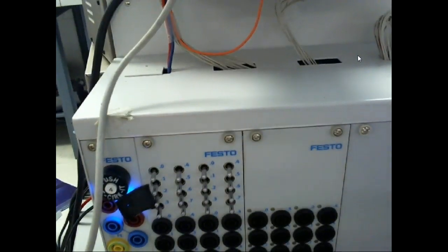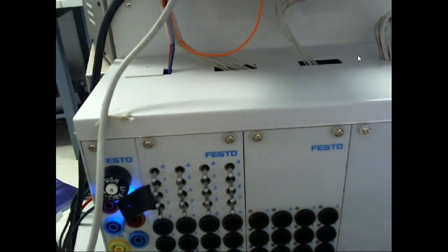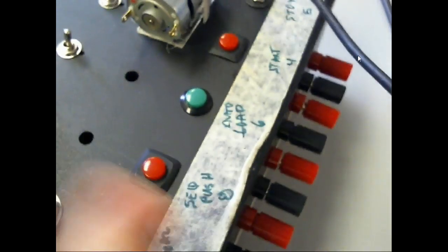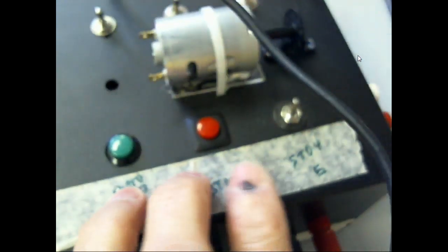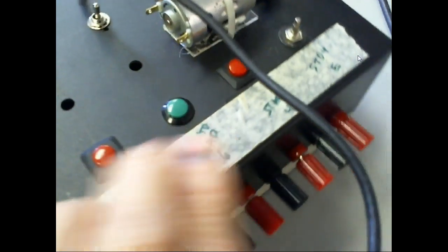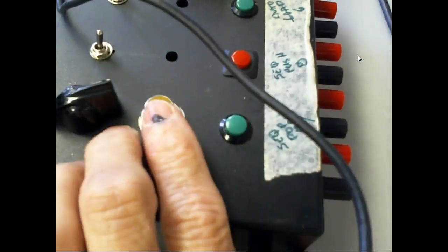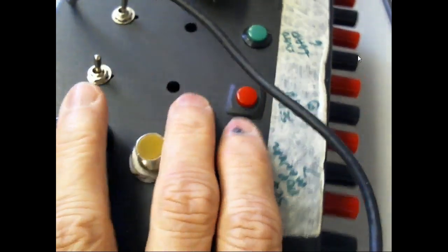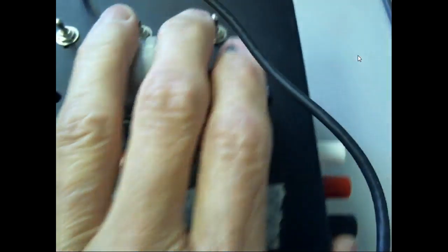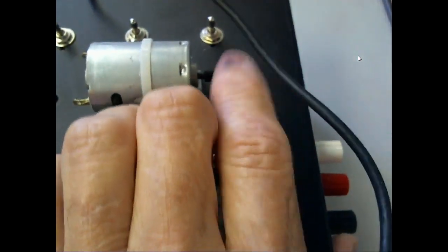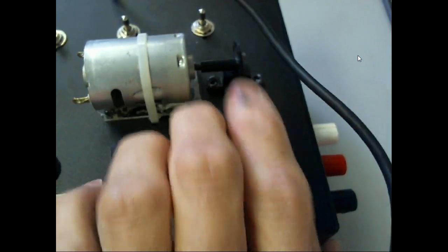Okay. So I want to wire up my inputs. So here's my inputs. It's on this box right here. And so I've got a bunch of inputs. I've got a normally closed push button right here. And then this is a normally open, a normally open, a normally open. This is a normally open. This is an inductive sensor. This is for analog, and then we've got some switches over here that we can use. This is a motor that's running an encoder, which we won't get to.